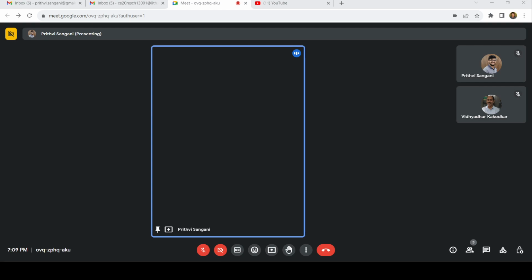This is another one, the same one, but I'm choosing the horizontal reaction at C as my redundant force. Let me name it now itself. So this is vertical at A, horizontal at A, vertical at C, horizontal at C. So I'll push this HC here. This is my redundant force which I'm applying externally.